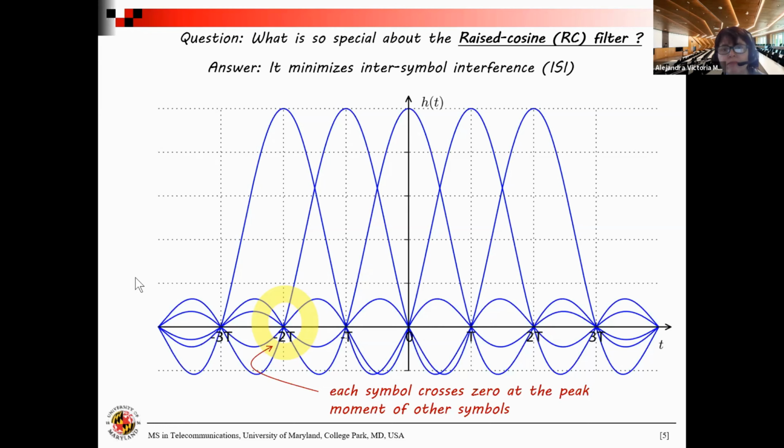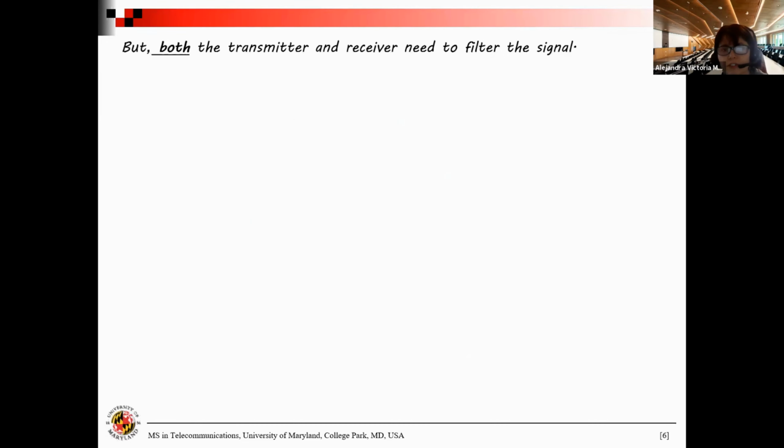All right? So if I ever ask you on a quiz or something what's so special about the raised cosine, you're going to say, first of all, it has less spectral regrowth. It has less spectral occupancy than a rectangle function, just plain, unfiltered signaling. And it has the wonderful property that it mitigates intersymbol interference. Okay?